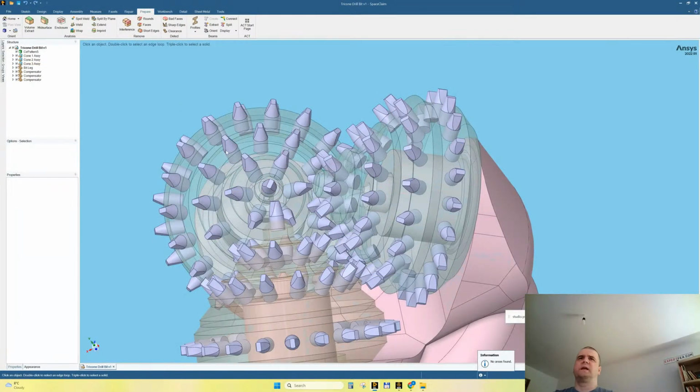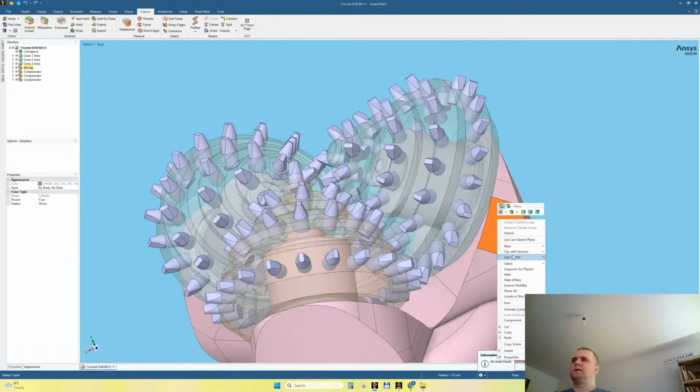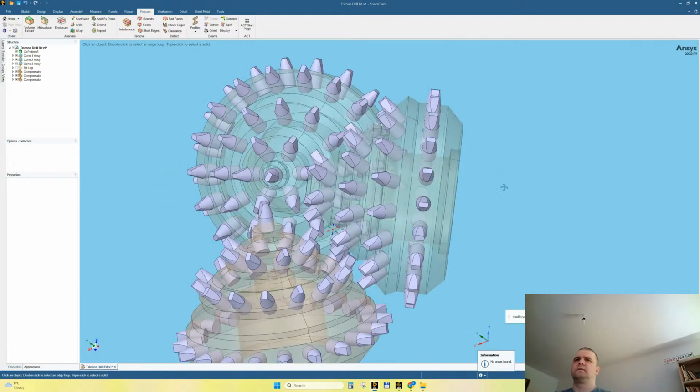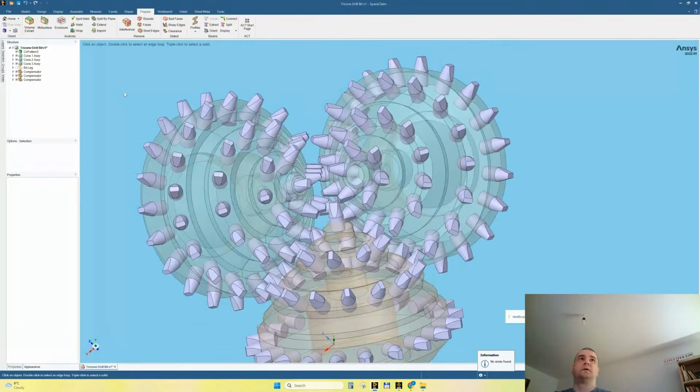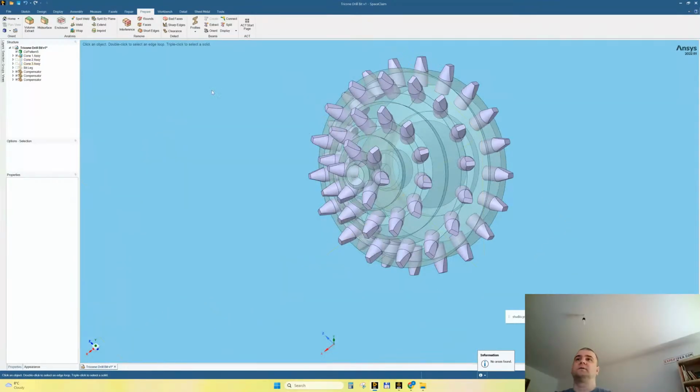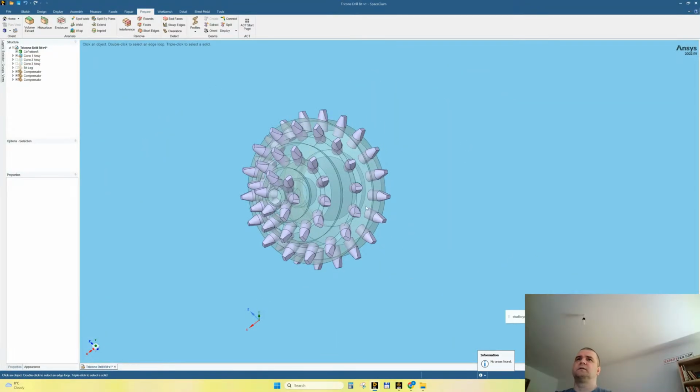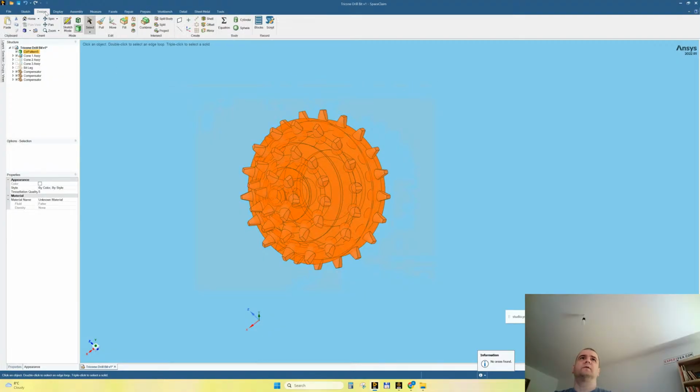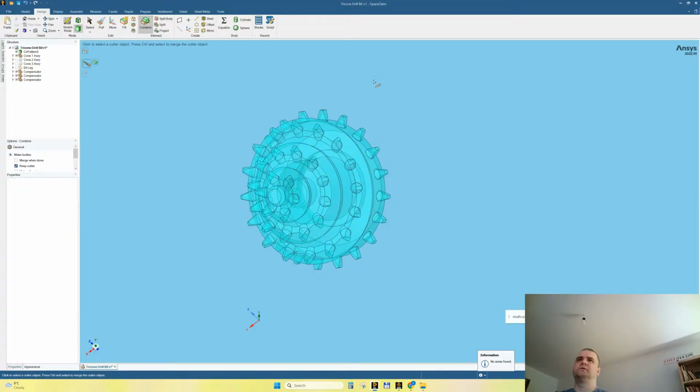All right, so escape, and let me hide the main fixture and other two. For example, let's go for design, combine, and we'll have a single part here. Look here, it looks so nice. One part. All right. So we repeat for the other way. Look here, it transformed from a sub-assembly into a single part.